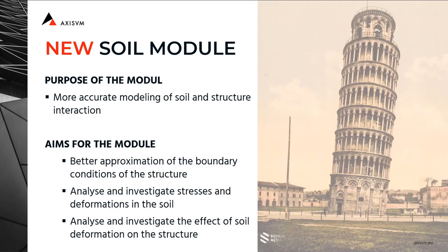The new soil module is a separate, general-purpose module which enables more accurate modeling of the soil structure interaction through the better approximation of the boundary conditions of the structure. The aim of the model is to analyze and investigate the effect of soil deformations on the structure and to analyze and investigate the stresses and deformations in the soil.